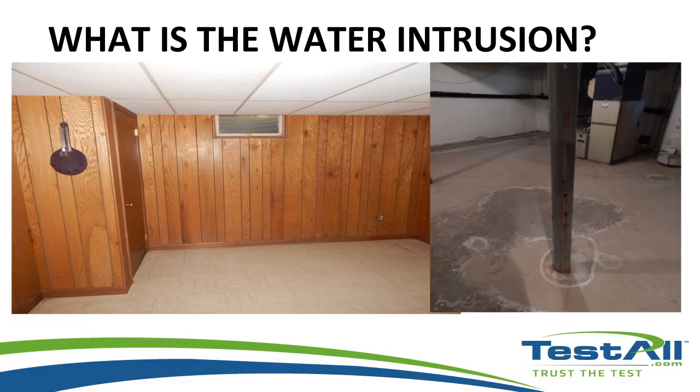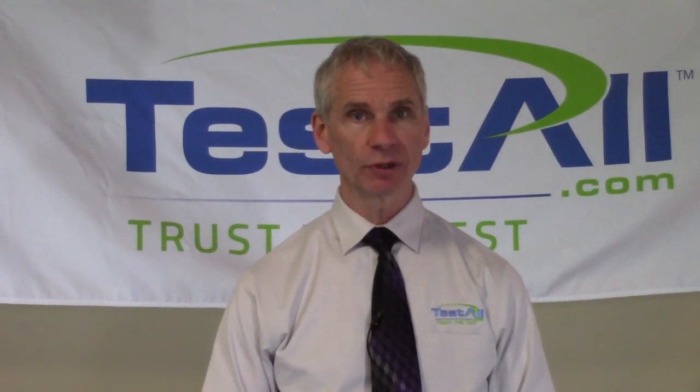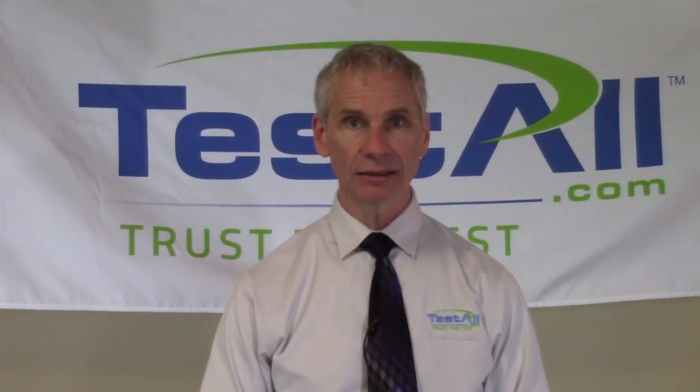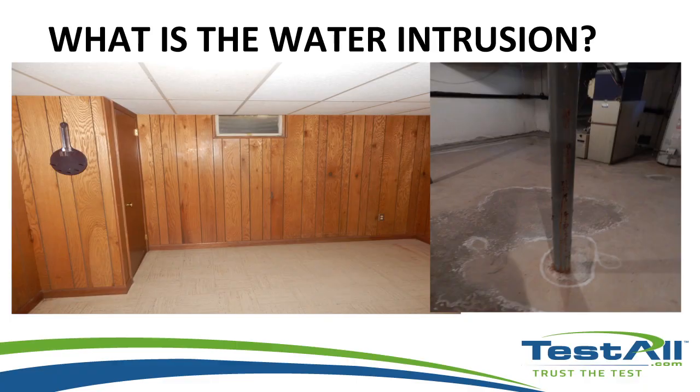We take a look here, you'll see this column, a steel column, cement filled, where moisture is actually wicked up from underneath the concrete into the steel column and starting to pit or rot the column. This is a common phenomenon that occurs when the moisture does wick up into the columns. From there, it starts to render the column less effective to do its job, to carry the load it was intended to. So there is a structural component to it. But there's also an indicator here that there's a moisture issue.